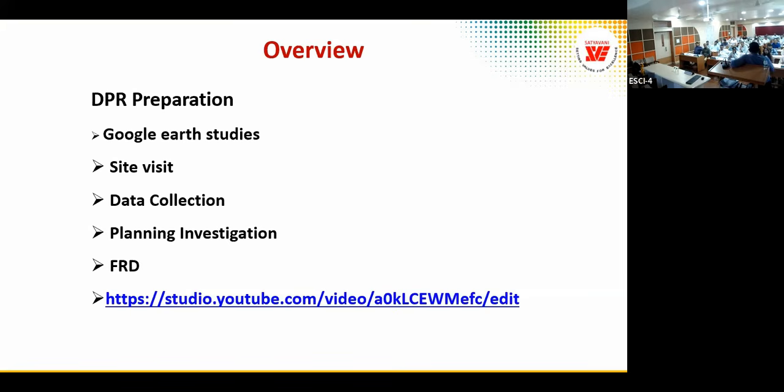Area eligibility for various designations like minister. We have seen that kind of projects also where the ministers ask for their whims and fancies. Can we provide it in the project? Scales of accommodation, sorry, that is the word. Whether it is a residential project or an office project or a government laboratory, for all, they're all well defined. So the implementing agency has to pick up the right scales of accommodation eligibility for all the occupants of the facility that is designed.